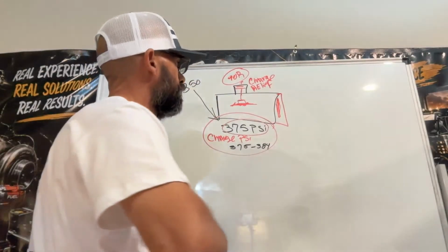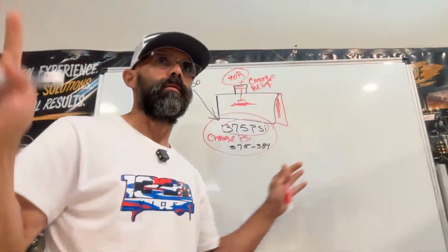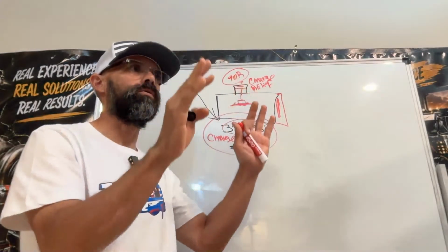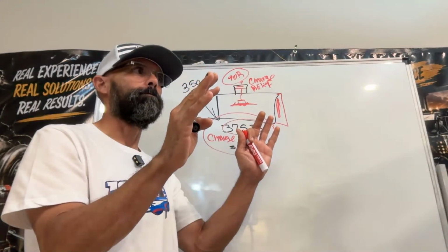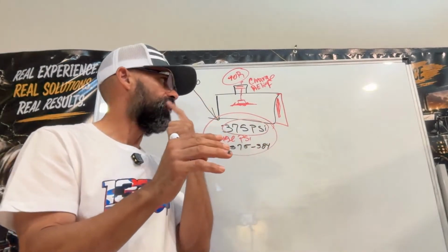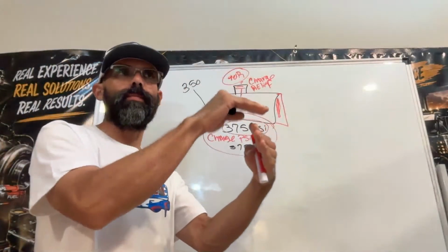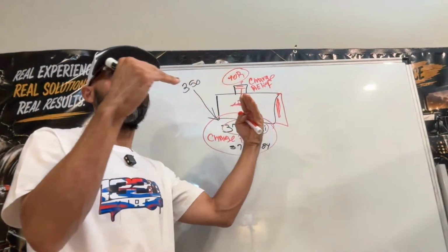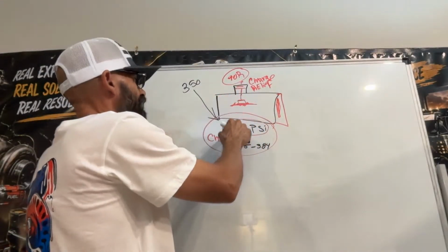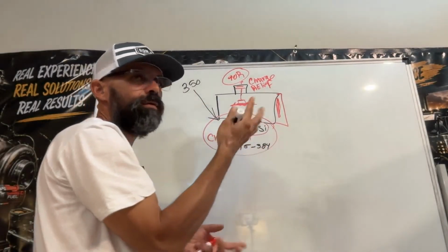Another thing it could be, I'm not saying that it is, it could be. So you've got to see the bigger picture. Do not concentrate only on one thing. When you're troubleshooting, ask yourself, okay, wait, what controls the charge pressure? I have a relief valve, and I have a charge pump, and I have this and that. Always break it down on a sheet of paper: this is everything for the charge system, right? So if you see that your pressure increases from 350 back to 375 or 384, that's okay.